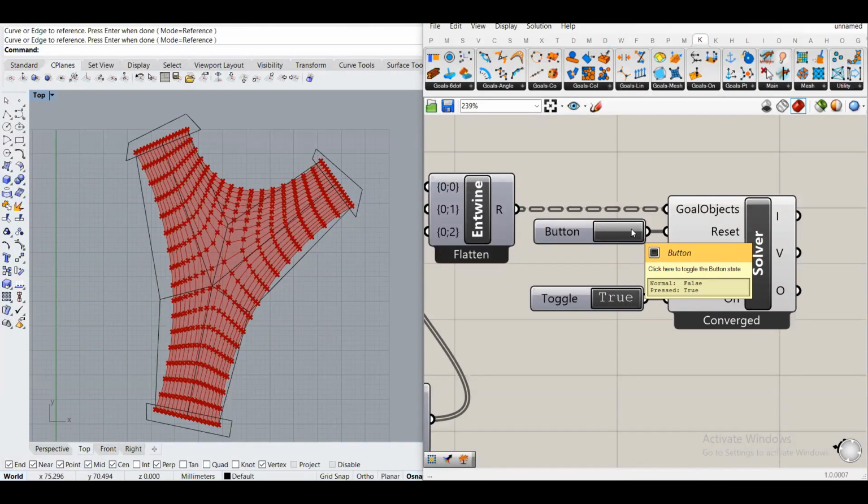Jiggly. Yes, it's also, yeah. The jiggly part happens because at the start of the simulation, there's a lot of pre-stress. There's a lot of stress in the structure. So when you hit go, when you hit the toggle true, it shoots out the vertices, the points of the mesh too fast, so they overshoot the target, and then they kind of find their equilibrium point later. And I'll be talking about equilibrium moments in a bit, but now at least we know that it works.